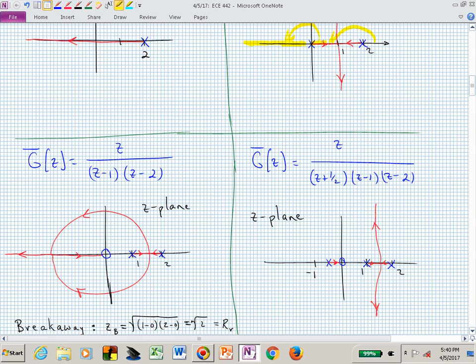What if I position myself now between the origin and 1 and I say, is this segment on the root locus? Now I have two poles that each contribute 180 degrees. The 0 contributes 0. The sum of all of that, the algebraic sum, is 0 minus 360, or 360. So those points between the origin and 1 do not belong to the root locus.